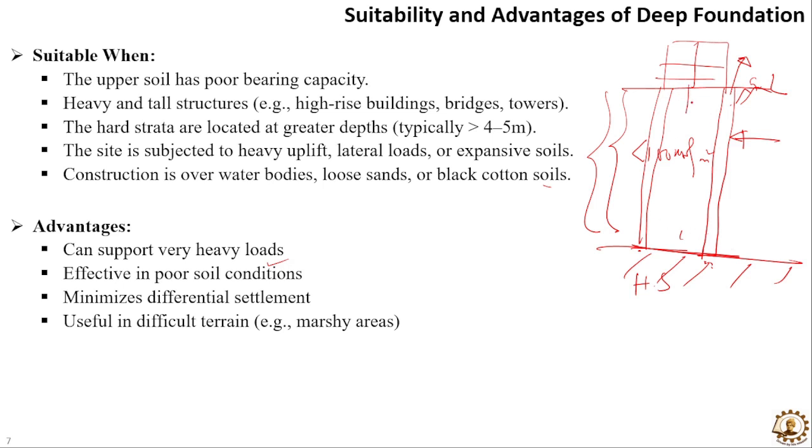But if we use a shallow foundation and the soil properties vary, suppose up to this zone the soil has one property and here a different property, the foundation will settle differently. So the chance of differential settlement in a deep foundation is very low, and it is also useful in difficult terrain.